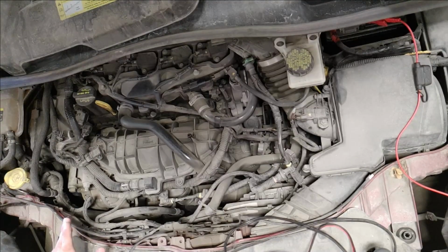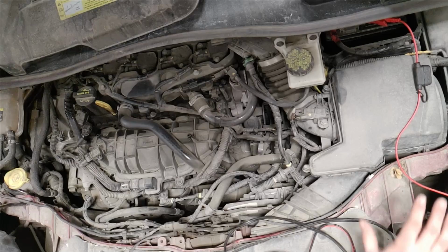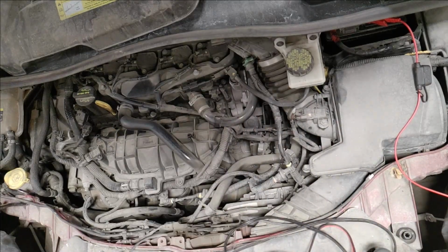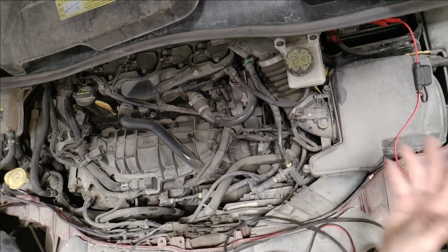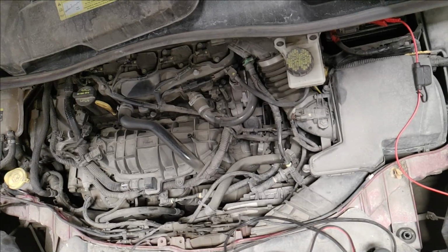So, how are we going to test this? Typically, I would just hook up a vacuum gauge to one side, but on this one, I can't really do that unless I remove all the intake system. And then my MAF sensor is going to be taken off, so the engine is not going to run properly. I might still have to, just to get to it, because I really do need to test it. Let's see what we can do here.